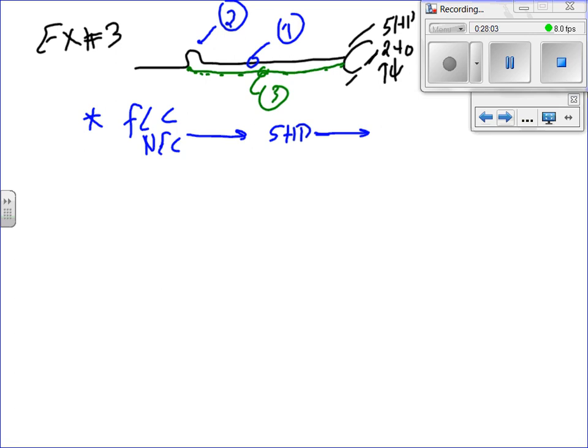Because there are so many manufacturers of motors, they don't agree on exactly what the full load current is. So they group them all in one table, and they said, well, this is the acceptable industry standard that you can use for the full load current of these motors under these voltages. So if you take the 5 horsepower motor, the table that covers single phase motors is 430.248. So you're going to go to table 430.248. It's a table, very easy to use.